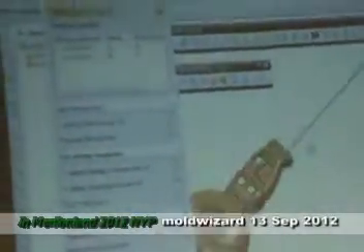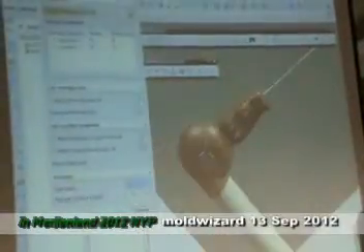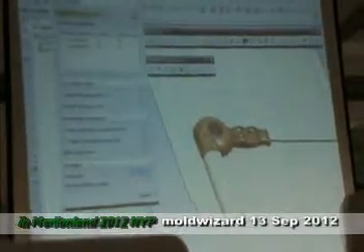It looks right, so just click OK. Now if you flip, you go to the other side, so it's wrong. You take it. Then how about the gap in between? The system will do it automatically. Okay, right? So we finished our parting creation.